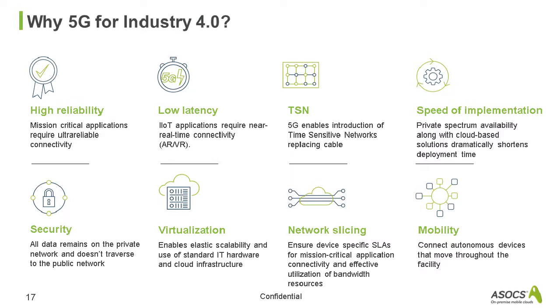But customers actually came to vendors such as ourselves and said, we would prefer to have the network at 7 or even 10 milliseconds, but we want to ensure the predictability and the low distribution of data, and that feature is called TSN. So in the industrial use case, high reliability and TSN are probably more important than fast internet and an ultra low latency aspect to the extreme of 1 millisecond.